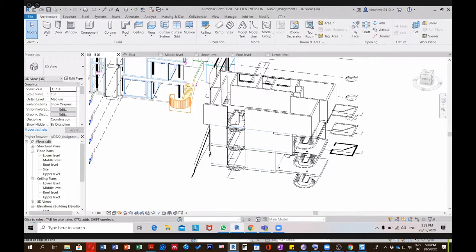I will just pick this one, but as you can see, I have to be careful what to pick, because if I pick this line, the wall will come to the center. So I will delete this. I will select pick, and for example, select the location of the line as core face exterior. So if I pick the exterior now, it should be correct.